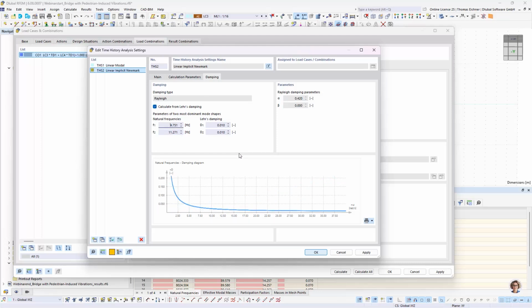So now let's talk about this damping approach for a minute, since I see a lot of confusion on it. This damping approach is something called mass and stiffness dependent damping. Mass dependent means the alpha value is a factor for the mass matrix. And the beta value is a factor for the stiffness matrix. In this way, the damping matrix can be described as a multiplication of those